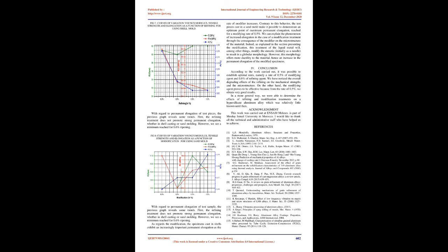Permanent elongation, A, %. With regard to permanent elongation of test pieces, the previous graph reveals some trends. First, the refining treatment does not promote strong permanent elongation, whether in shell casting or sand molding. However, we see a minimum reached for 0.6% refining.